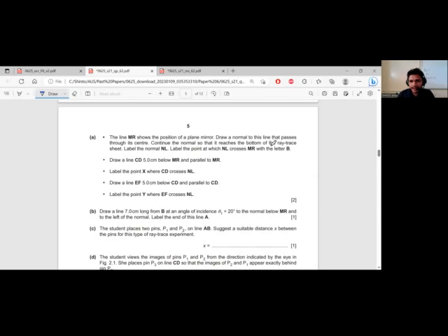I'm just reiterating the things that you have learned in lower grades in math. Now, if you want to draw a normal or perpendicular that goes through the center, how should you draw it? You take a line, you take a length in the compass that is more than half of this line, make an arc from here, arc from here, arc from here, then arc here, and connect it. You will be able to draw a perpendicular bisector. These are geometric techniques that you should be aware of.